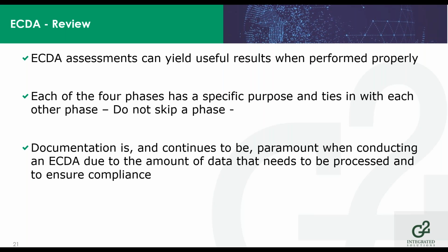Documentation is always, always, always an issue for operators. This is a large data pull to do a project like this, but it is imperative that you're documenting everything. You're maintaining your documentation. It's good for you as an operator because it gives you data to use when you're doing your integrity assessments, you're making decisions about what you're going to dig, what you're going to repair, and then it also demonstrates that you're in compliance with the regulations when you're going to be audited, because you will be audited.